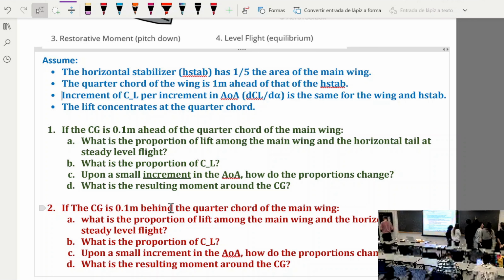And the ratio of these two lifts is exactly equal to 1.1 over negative 0.1 initially. So you can also write this as 0.1 times lift of the wing times 1 plus 1.1 over 0.1 times lift of the tail over lift of the wing.